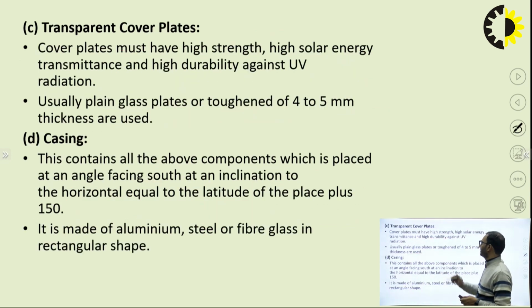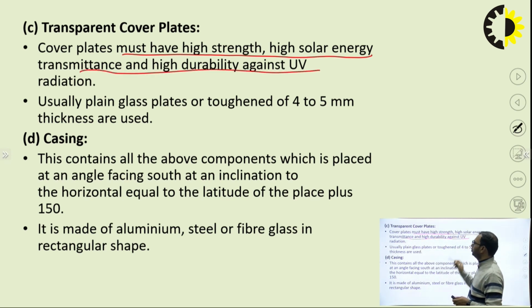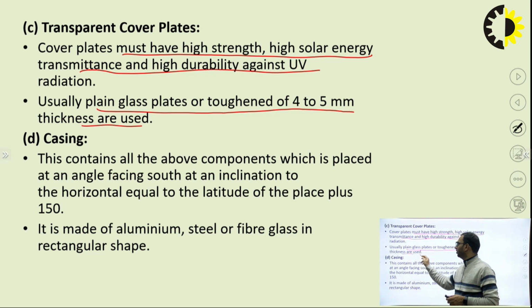Now, the transparent cover plate must have high strength, high solar energy transmittance and high durability against UV radiation. So, usually toughened plain glass plates of 4 to 5 mm thickness are used.